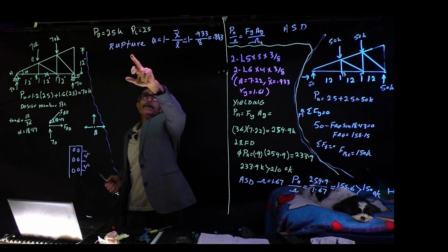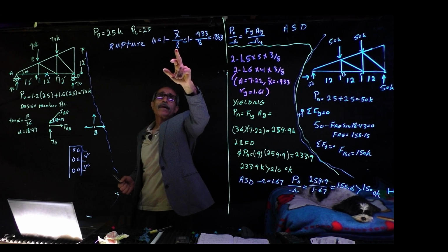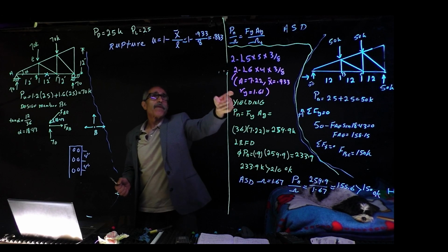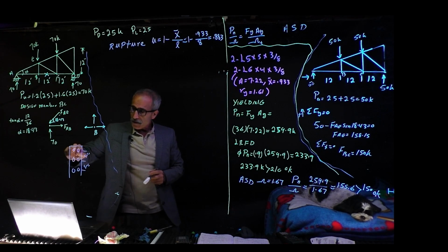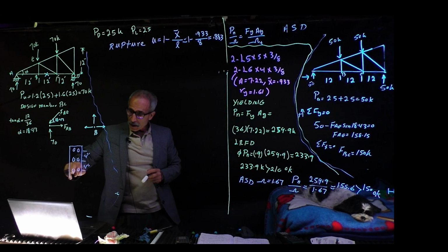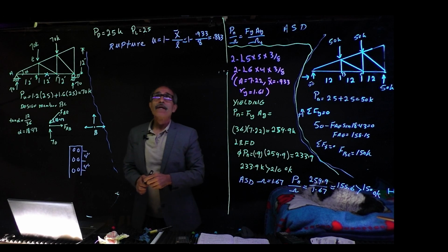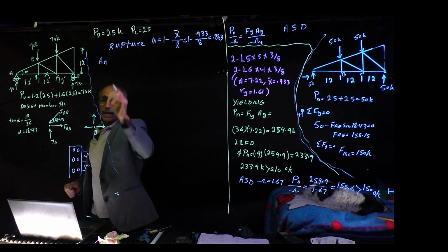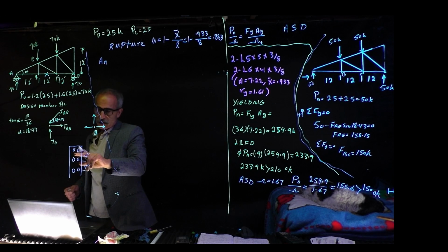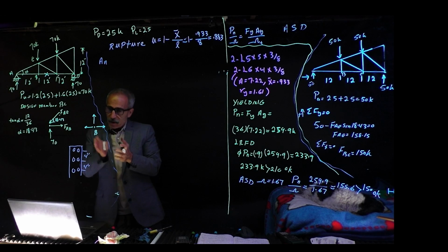We're going to do the rupture, and the equation we just had before the erase is U equal 1 minus x bar divided by L. X bar we got from the table, 0.993, and L is 8, basically from the first bolt hole to the last bolt hole, which is 4 and 4, that's 8 inches. So now we have that, and then the next thing we're going to calculate the net area. Remember, if I look at the cross section of the side, we got 2 holes in 1 angle, and 2 holes on the other angle, so there's 4 of them.